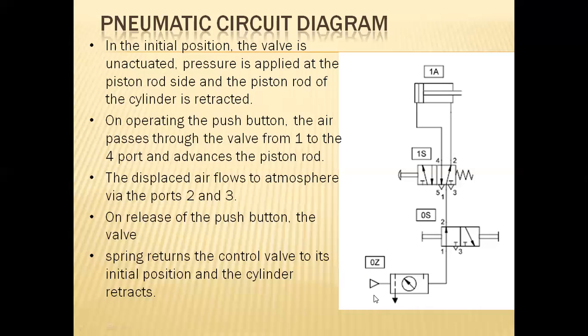Here it clearly specifies that the air, compressed air from the compressor, enters the FRL unit initially. And here we have the representation for the filtration process. The filtration process means the tiniest particles will be filtered out instead of entering from the hose pipes to the cylinder.